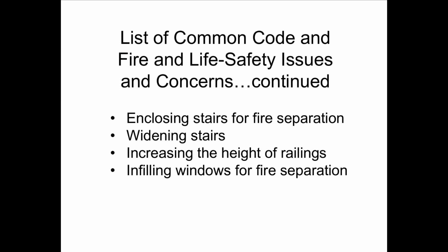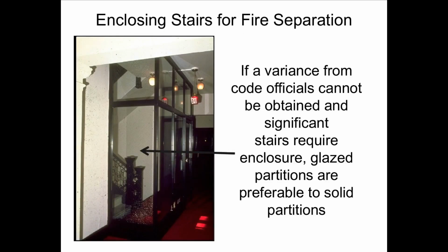It's a continuation of that list of issues and concerns. Enclosing stairs for fire separation, widening of stairs, increasing the heights of railings, and infilling windows for fire separation. If a variance from a code official cannot be obtained and significant stairs require enclosure, glazed partitions are preferable to solid partitions.